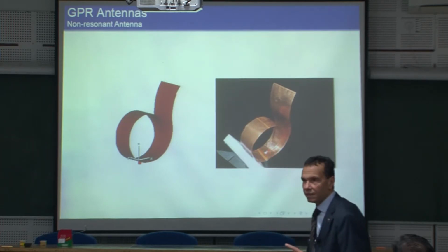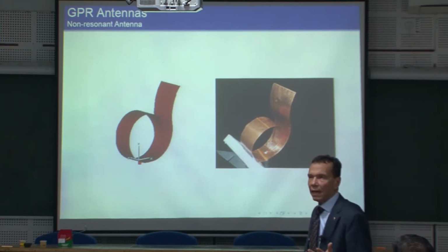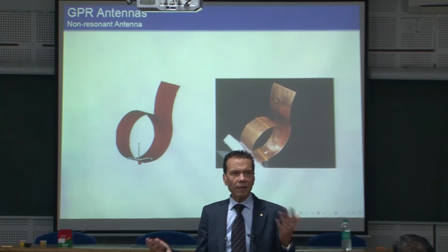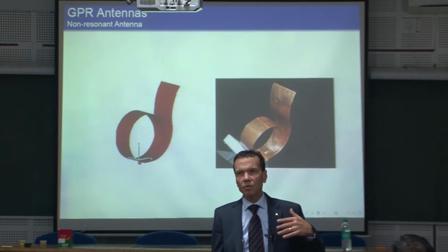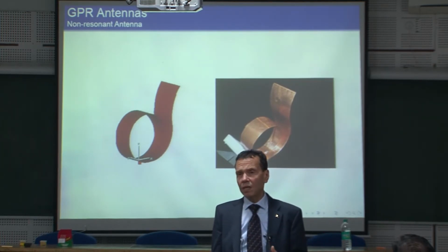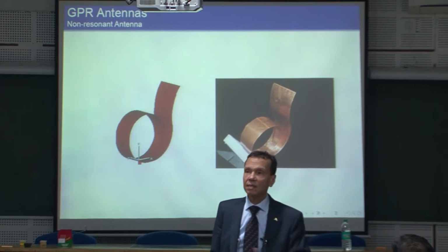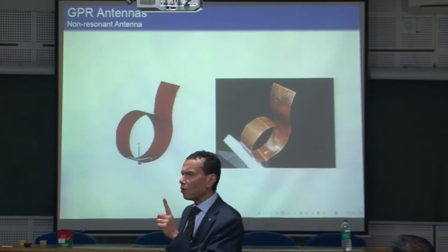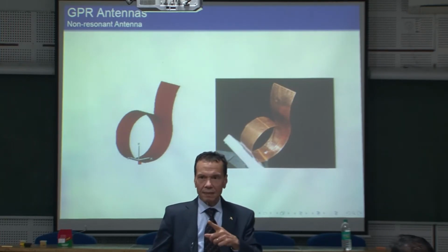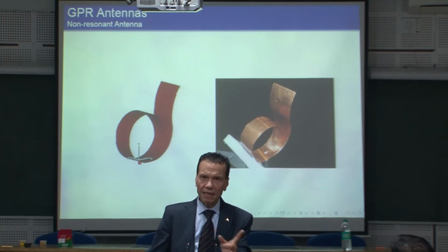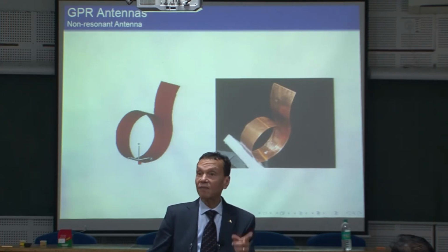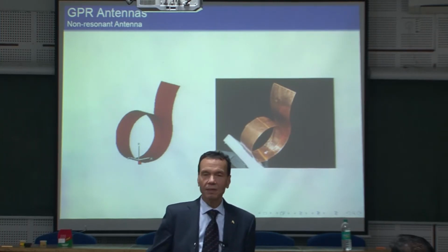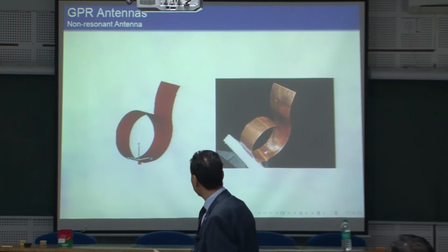This small thing here is an electric dipole. And I have now an electric dipole and a magnetic dipole. I have electric energy stored and magnetic energy stored. I have resonance, and you can have this resonance over a wide frequency band. So at each frequency you have resonance. Because don't forget, narrow band means the passband, where the system is at resonance. And right and left, the system could be inductive or capacitive. But if you succeed to have continuous resonance, multiple resonance at each frequency, this was his explanation, and it was really very, very wide band.